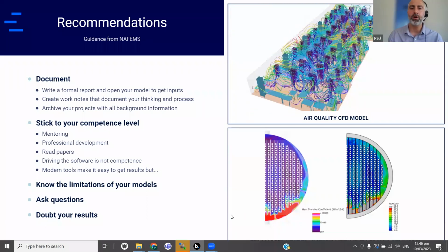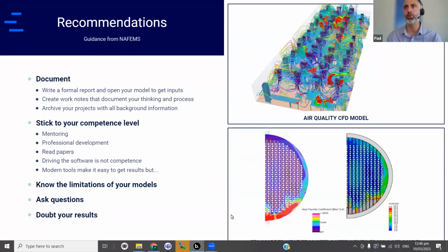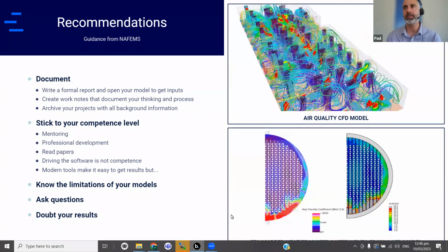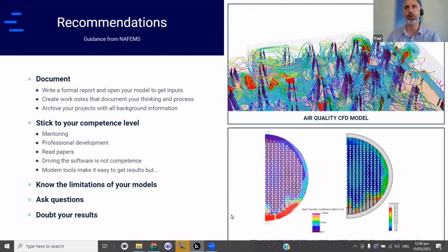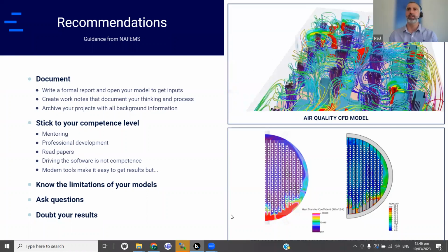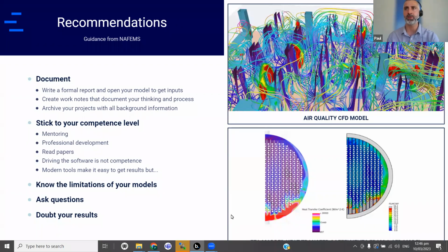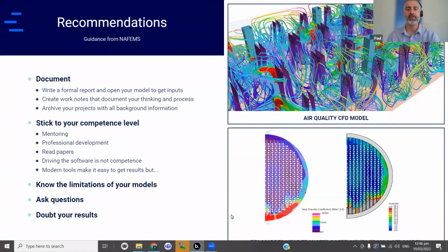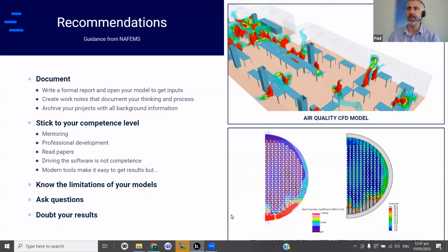Well, I think mainly sensitivity. The big thing for sensitivity for me would be areas where there is uncertainty in your model, any aspect of your model where you know there's uncertainty. Maybe that's a boundary condition, probably more relevant to boundary conditions, because it's a classic situation in an FEA model. You need to constrain your body in space, you need to constrain all 6 degrees of freedom.